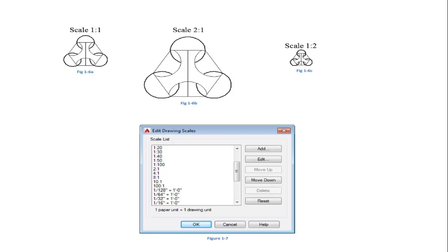We can see some of these ratios down here. If we actually get into our AutoCAD program, and this is shown on page 9, we have a list of scales. When we get into sheet files and viewports, we can see there's our 2 to 1 scale. This would be 2 times the actual size. If we were able to flip this up and down, we'd see some of our more normal scales. So we know 1 inch equals a foot is going to be a 1 to 12 ratio. That is what we tell the computer we want to scale our drawing down to fit on that paper, so it'll do a 1 to 12 ratio. Very easy to conceive of.